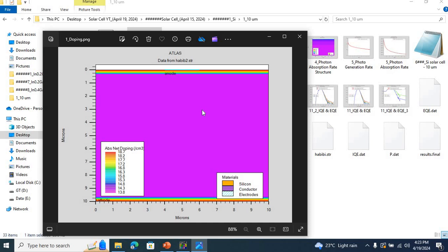So it has shorter wavelengths, medium wavelengths, and longer wavelengths. Materials have higher absorption coefficient for shorter wavelength light. So shorter wavelength light can travel only shallower into the material, close to the top surface. Similarly, medium wavelength light can travel a medium distance inside this structure, and longer wavelength light can travel deeper into the structure.